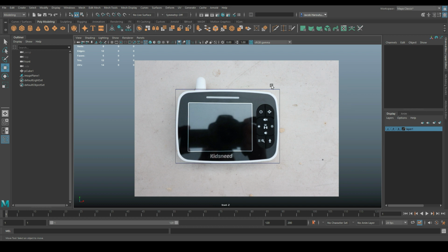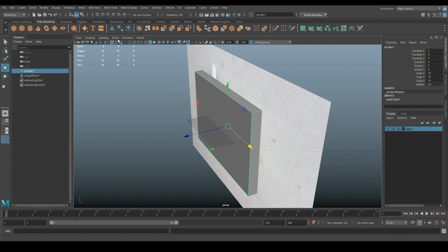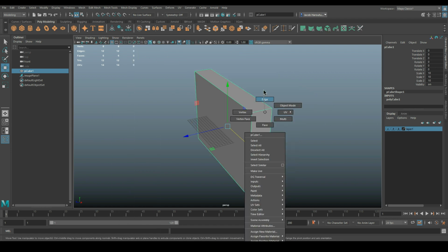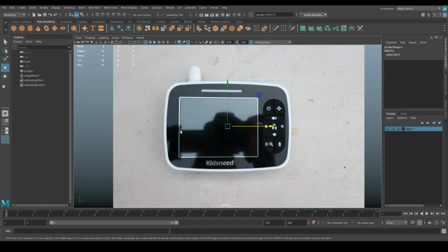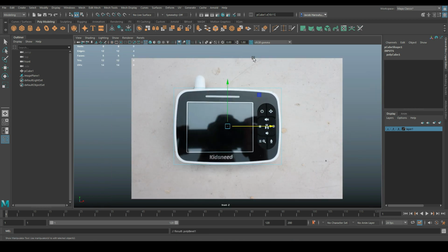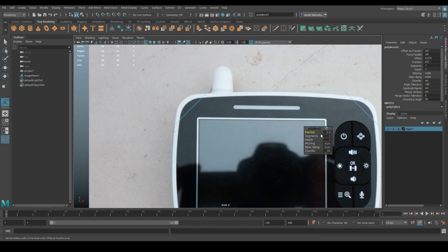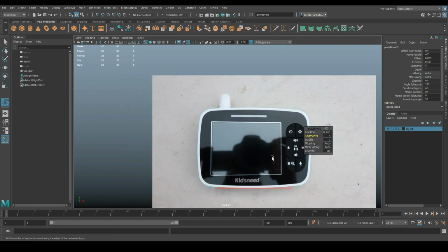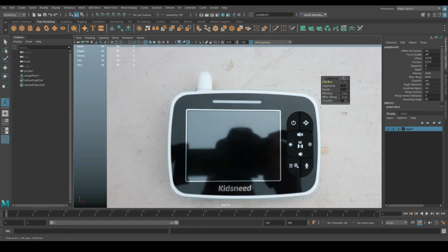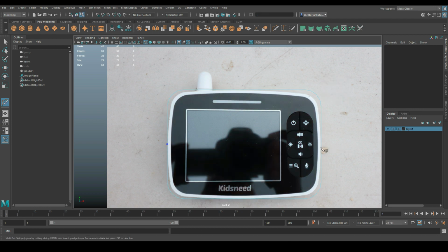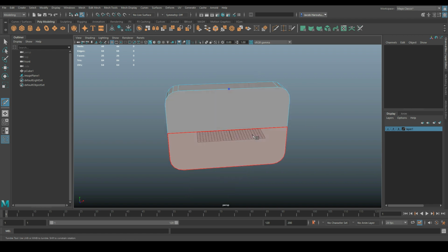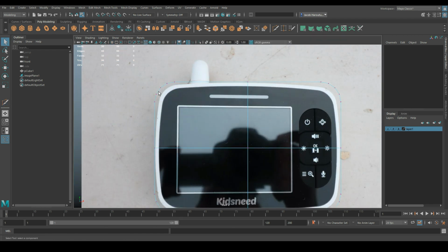Now that I know that this is lined up, I'm gonna get the bevels in. So I'm actually gonna hide the image plane here. I'm gonna go ahead and click the 4 corners here, and I'm gonna click Shift, right mouse button, bevel edge. And as you can see here, we got a nice bevel going on. So I'm gonna slow down the intensity of how much you can extend this, and I'm gonna start adding segments. All right, I added 4 segments there. That's looking pretty good. Then to match the shape of this here, I'm gonna adjust the bevels, and that's looking about right. I'm gonna work on one side here. Then I'm gonna go ahead and add an edge here in the middle, make sure it's going all around, and one on the top here, so that we can get some good modeling in here and match the actual device.